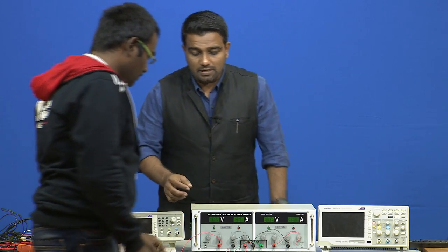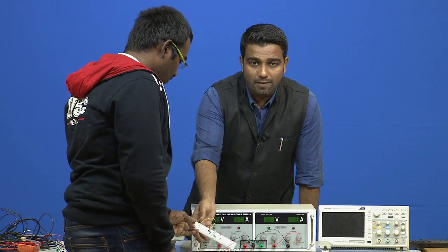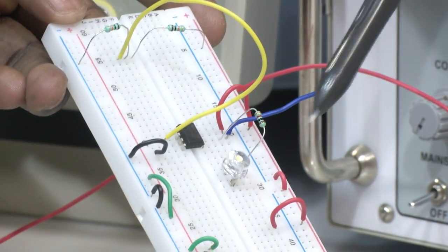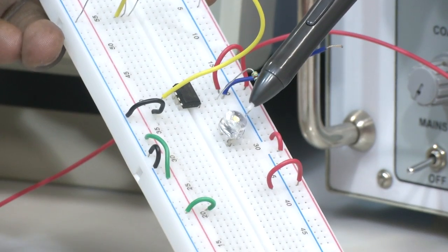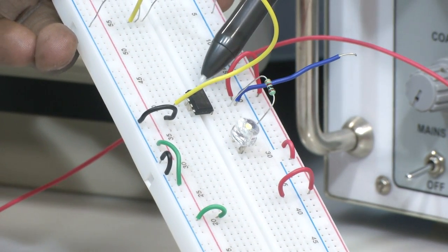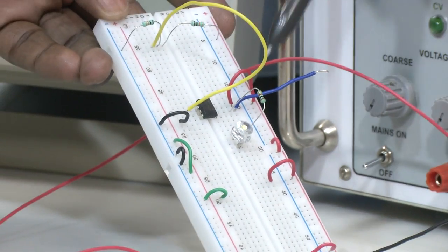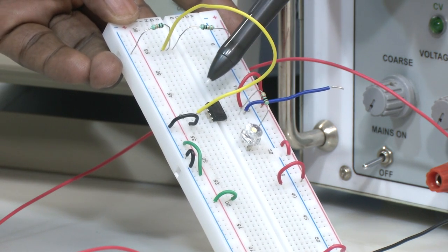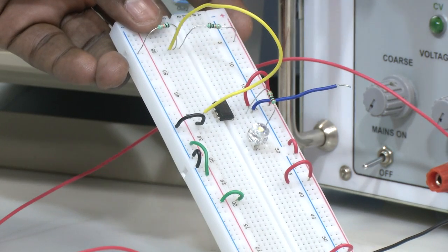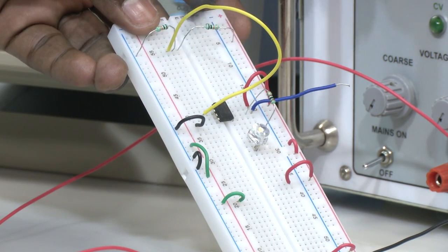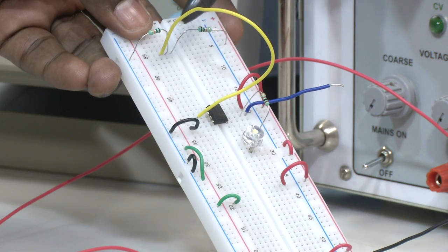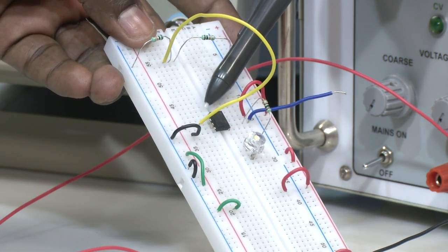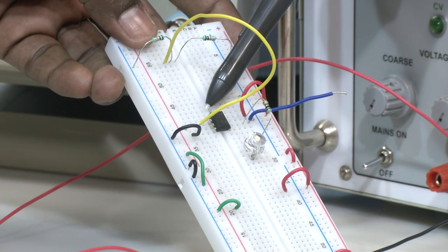You see here on the breadboard an LED, and then the op amp, and then you have the current limiting resistor to the LED, and you are applying V reference through the potentiometer or through the potential divider, the two resistors, to the inverting terminal of the operational amplifier, right.